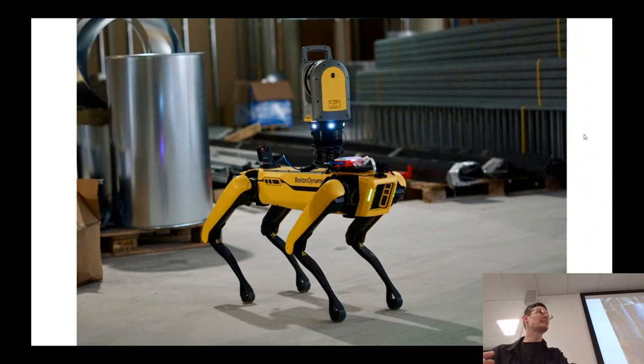This is just like a really expensive version of that. But it scans that and then produces a digital model of what you're doing. And then you can compare that to the model that you've made and say, hey, listen, this pipe that the engineers installed is 2 feet to the left and it should be over here. There's a problem. And you catch it well before it becomes a real issue.